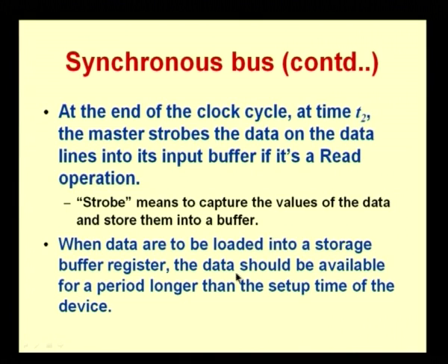Okay. So when data is to be loaded into a storage buffer register, the data should be available for a period which is longer than the setup time of the device. Since I have to store it into the buffer, remember whenever we store into any buffer, which is essentially any memory component, there is something called a setup time and a hold time. So you need to make data available before the setup time, and you need to hold the data for a little time which is more than the hold time. Okay. So both these have to be taken into account when you are deciding on the clock pulse width.